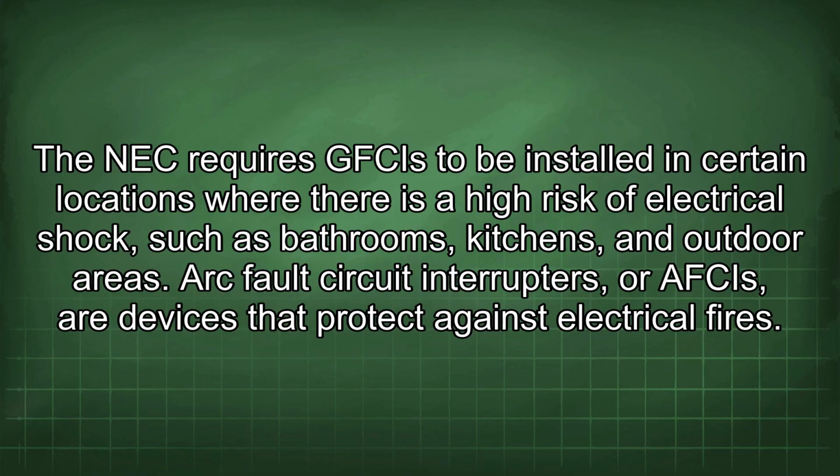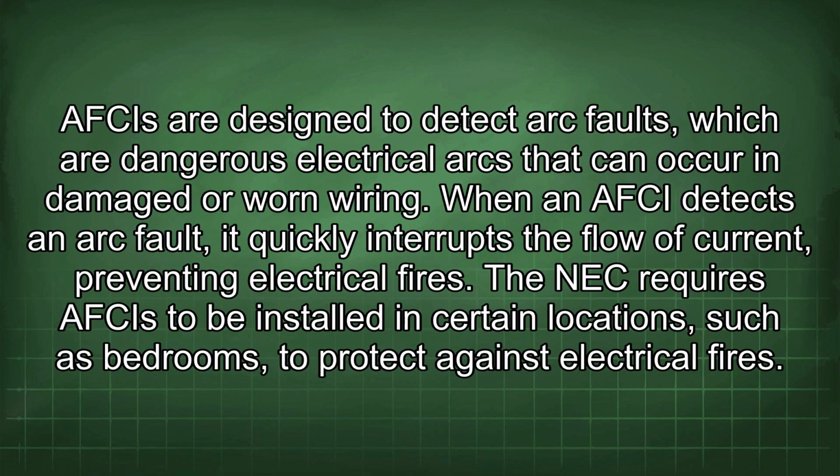Arc fault circuit interrupters, or AFCIs, are devices that protect against electrical fires. AFCIs are designed to detect arc faults, which are dangerous electrical arcs that can occur in damaged or worn wiring. When an AFCI detects an arc fault, it quickly interrupts the flow of current, preventing electrical fires. The NEC requires AFCIs to be installed in certain locations, such as bedrooms, to protect against electrical fires.